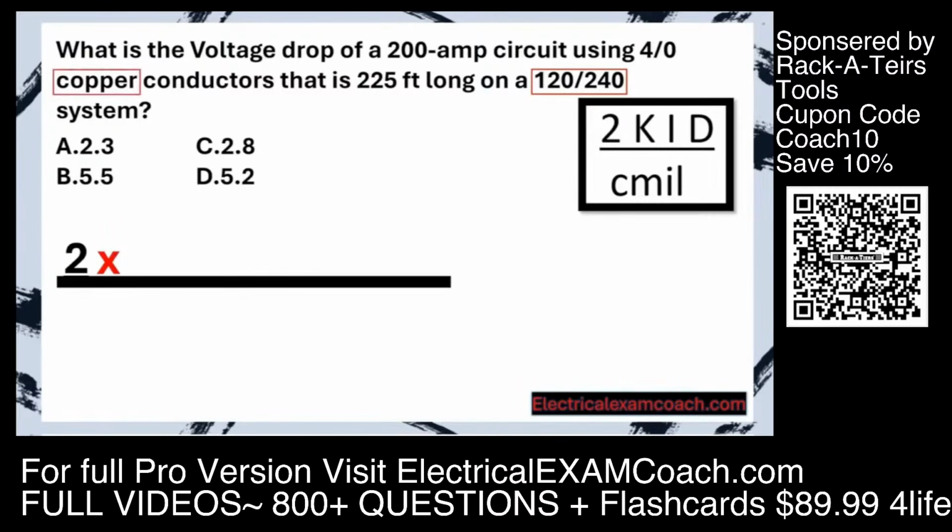And in this case, it's copper. So the K factor for copper is 12.9. Now we need to look at I, which is current. We put down our X for our multiplier. We go to our question, and it's a 200 amp circuit. So we're going to put 200 down. Then we put our multiplier, and now we need to look for D. Well, our D is 225 foot, and we put that down.